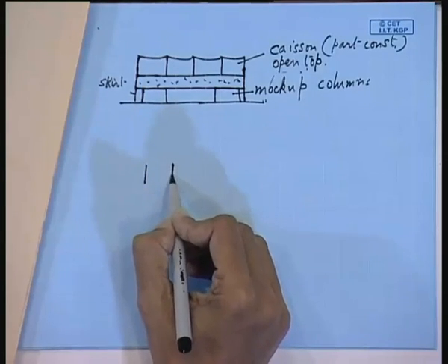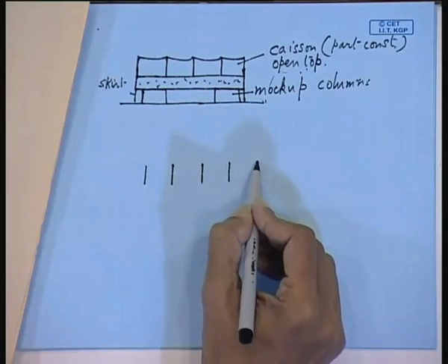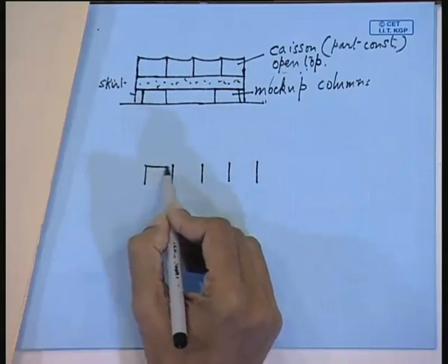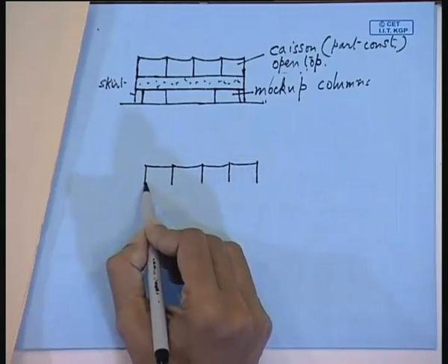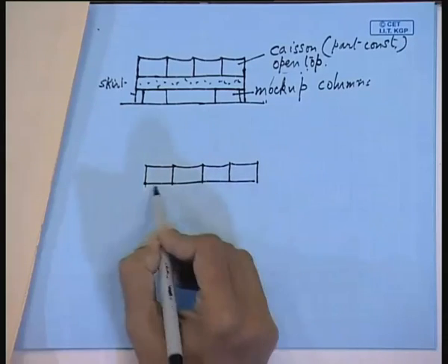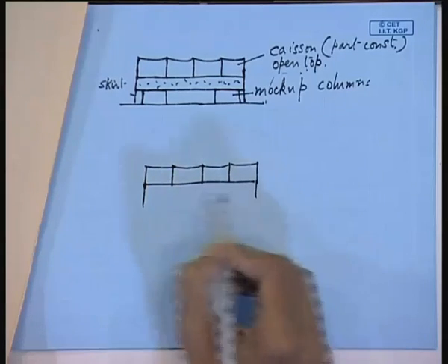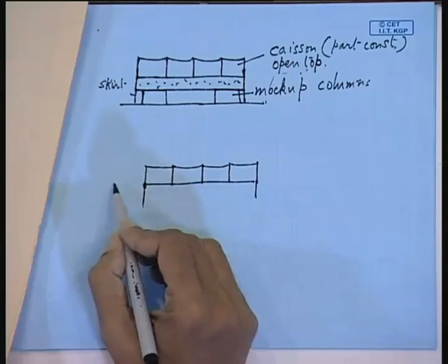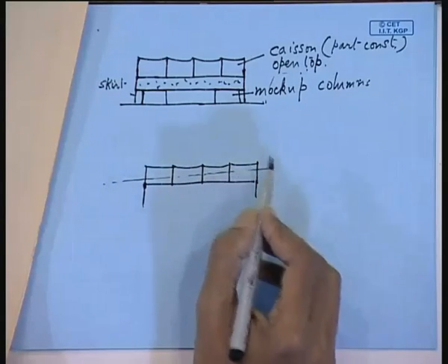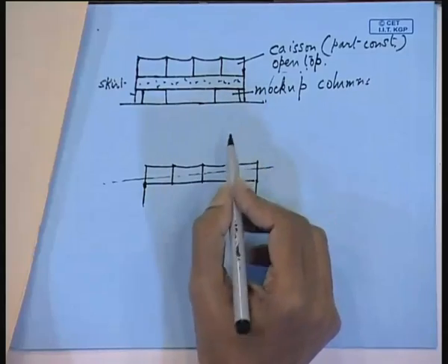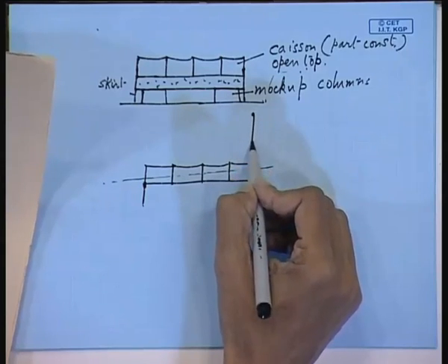Now here actually you have to be pretty careful. Why? Because on the one hand you are having a traveling crane. So here you have to do your hydrostatic and stability calculations, and you will find that the whole structure is tilted. If you have a crane like this at one side, as is shown in the picture, then that will cause a heeling moment.